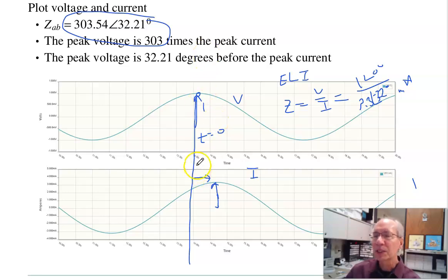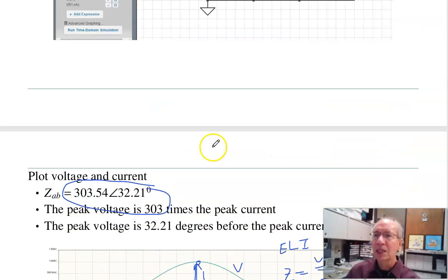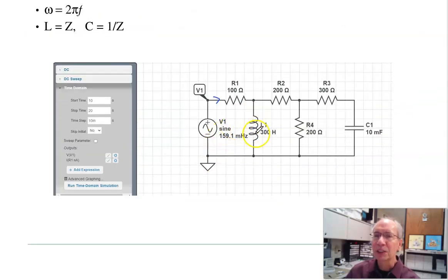So this is how you find it experimentally. Apply a sine wave in, measure the output, take the ratio, well, correction. Take the voltage, measure the current, take the ratio, that's the impedance. That's how you experimentally find the impedance of the circuit.